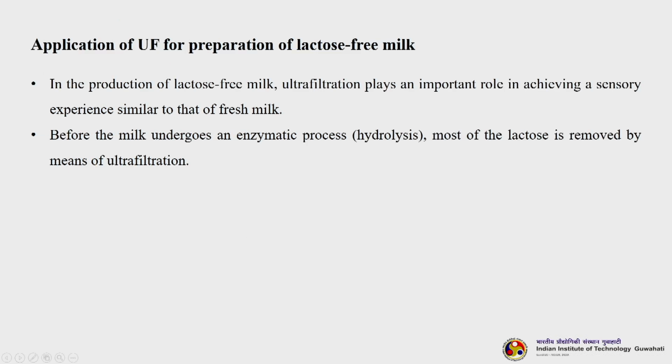Application of ultrafiltration for preparation of lactose free milk. In the production of lactose free milk, ultrafiltration plays an important role in achieving a sensory experience similar to that of fresh milk. Before the milk undergoes an enzymatic process, most of the lactose is removed using ultrafiltration. Again, remember, in industries a single stage or single step ultrafiltration membrane will never give you the desired result. So, everything is done in stages, or you can call it in series.